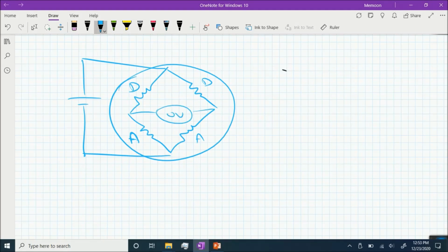No matter how much temperature increases, the resistance of all these four sensors will increase or decrease equally, and the net effect of them will be cancelled out at the differential output of this bridge also, as we can clearly see here in this equation.